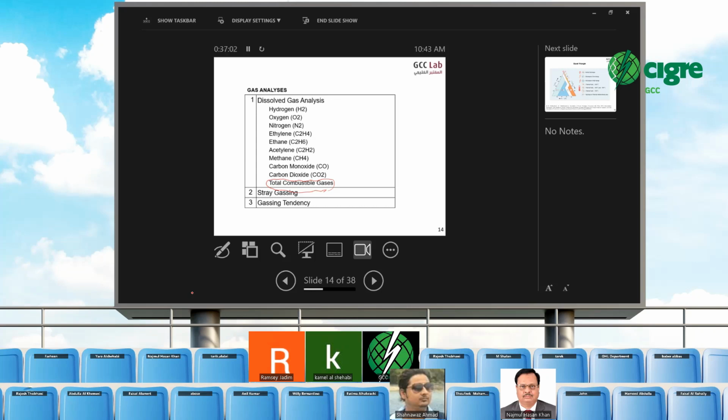If there is aromatic or not, less aromatic or high aromatic is affected. Oil with high aromatic has a capability to absorb the gases, but with very low aromatic, it can release the gas bubbles. But the problem also, you cannot go very high in the aromatic percentage, but there is an optimized aromatic percentage. I think it's around 8%.